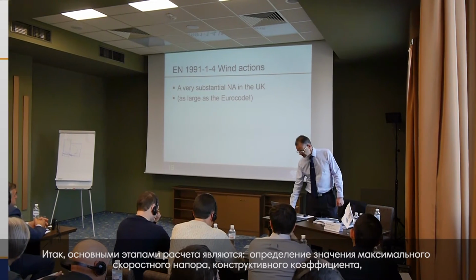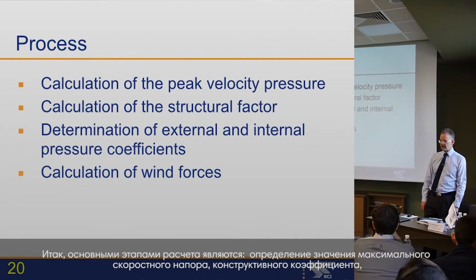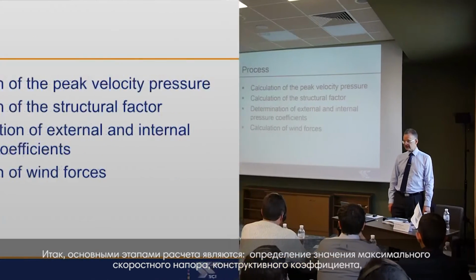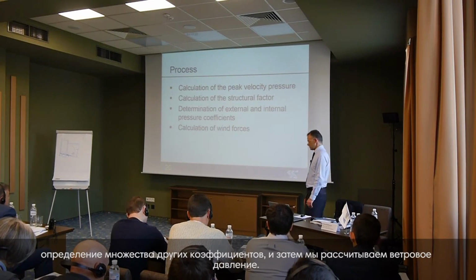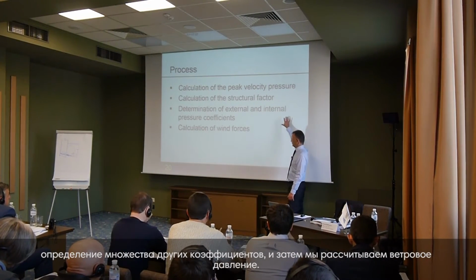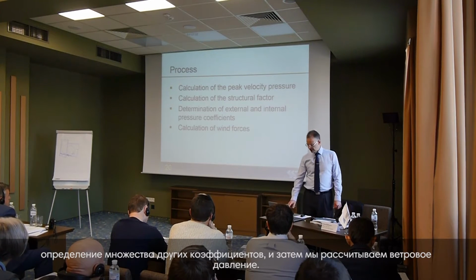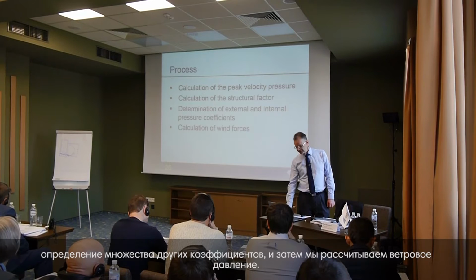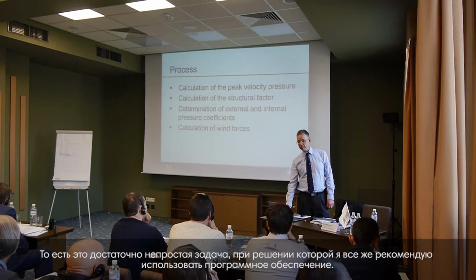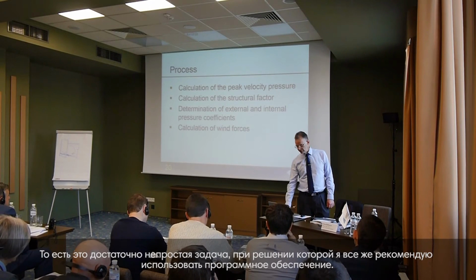So the basic process is that we calculate a peak velocity pressure. There is then a structural factor. There are then lots of coefficients, and then we can calculate wind forces. So this is not a straightforward task, and I would still recommend that you use software.